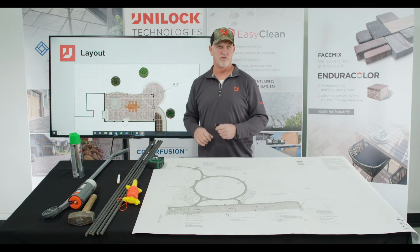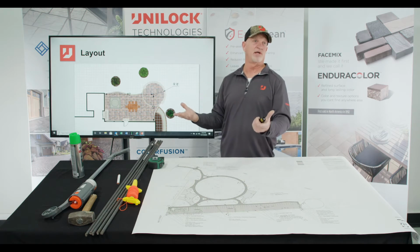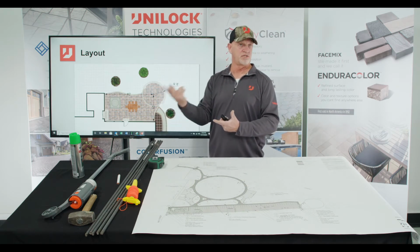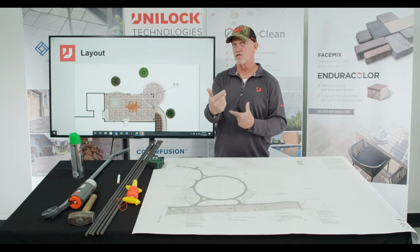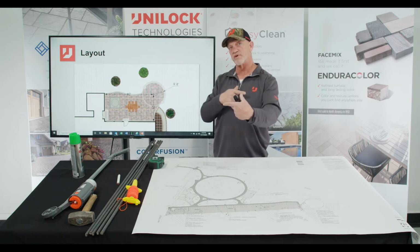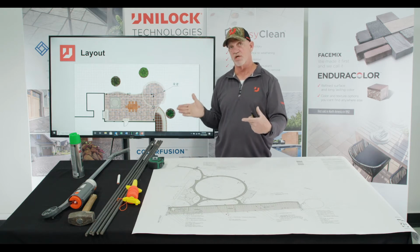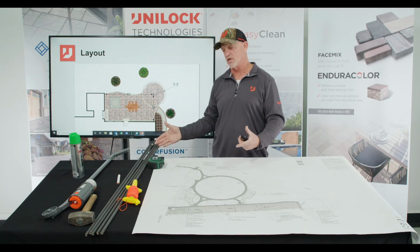Spray paint, obviously marking paint definitely has been the improvement over hose layout, if you will. I like 2 colors of paint because it identifies different features so that I can communicate with that crew exactly what they should be doing. So remember in that earlier drawing with that dotted line, I like using a different color paint so that my crew behind me is doing the excavation in accordance with that extra color in maintaining that outside edge.